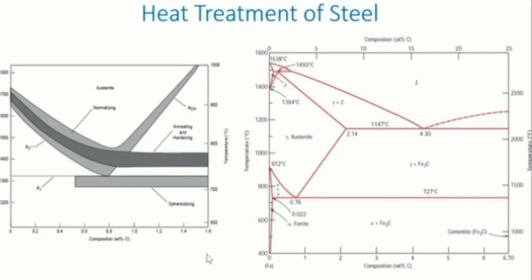So similarly with full annealing. Full annealing is this dark ash. You can see it looks like an L, though it's a sleeping L. So it starts here. Can you see? It comes here, then it goes parallel. So this is the A1. A1 is the eutectoid temperature. Can you see? This is the A1. So it means you must heat within this slanting L. The left side of the L is a bit slanting, while the other side is perfectly horizontal, right? So you must heat at least above this L.